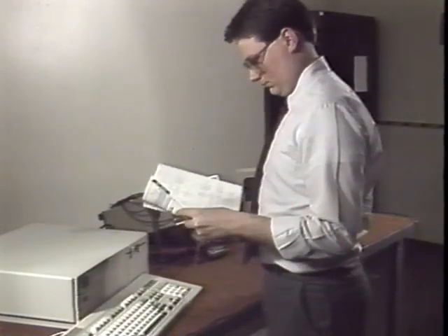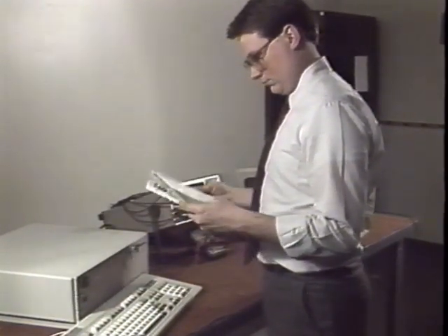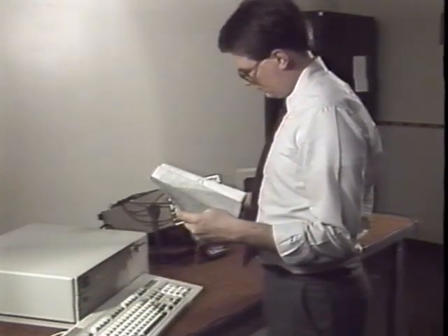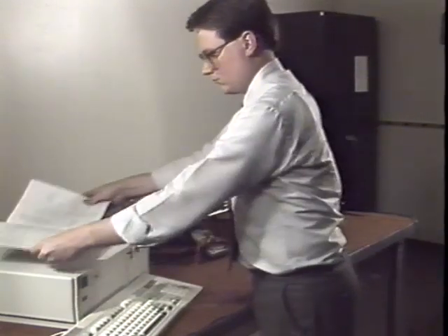In this tape, we will describe a general order of alignments, but always consult the manual for specific instructions on any monitor. Also, if one alignment is grossly incorrect, you may want to rough it in before beginning the regular alignment procedure. Before beginning a monitor alignment, let the unit warm up for about 15 minutes. This will allow the various components to reach a stable operating temperature before you start.